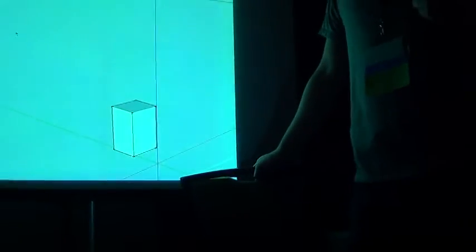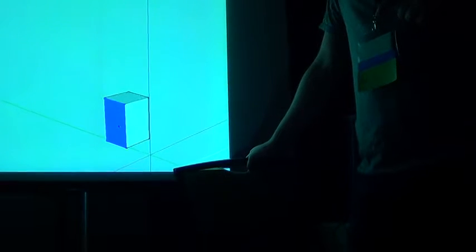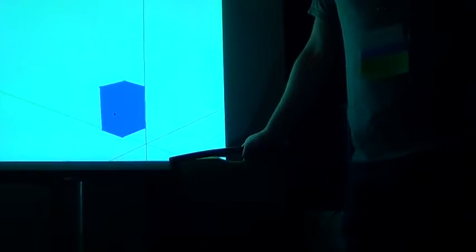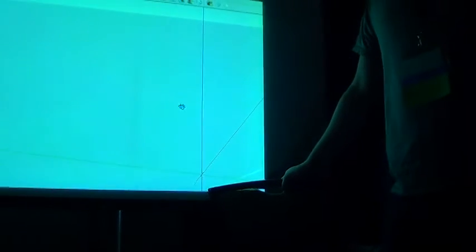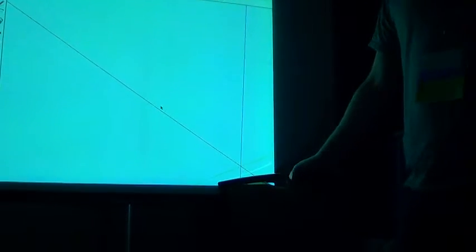So most of the printers now have multiple material types they can print with. ABS is fairly common. A lot of people print with PLA, which is a cornstarch-based material, so it doesn't smell nearly as badly as ABS when you print with it, but it's also much more brittle. There's HDPE, which is like what you find in milk jugs. You can print with that at a lot lower temperature. It's a little hard to find in the media that you might need.